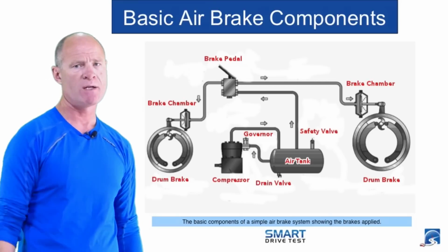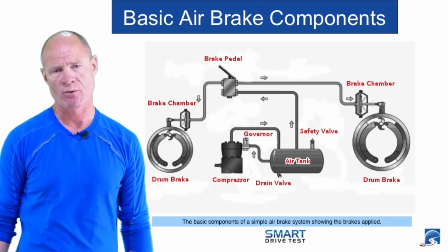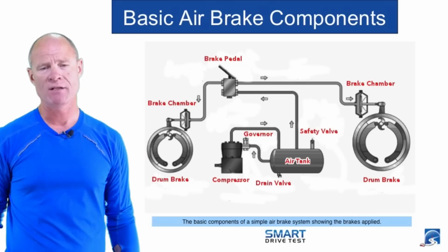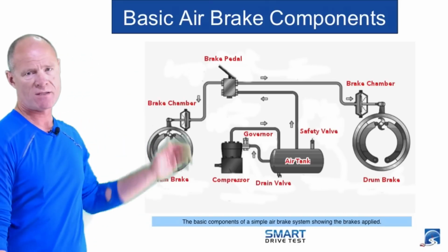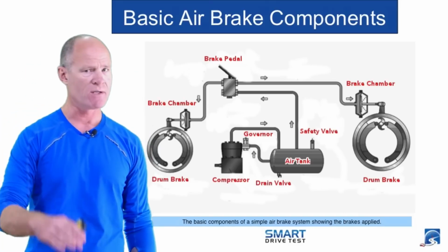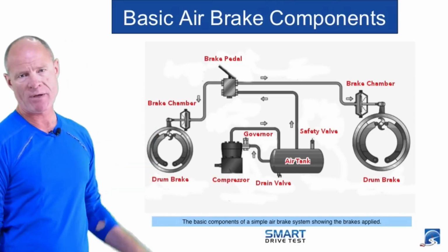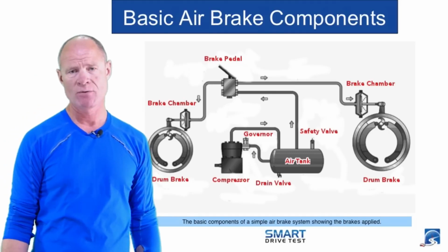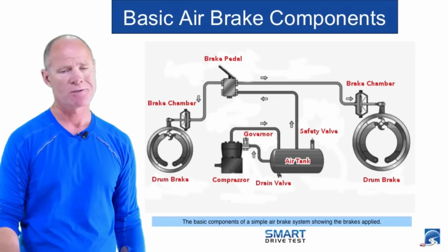That's equipped with air brakes, the service brakes, and the spring brakes. The spring brakes are primarily used for parking and, in the event of an air loss, also for emergency brakes. But for this fundamental system, these are the service brakes, the brakes that you use going up and down the road after you release the parking brakes. The brake pedal can also be called the foot valve or the treadle valve, but for simplicity, we just call it the brake pedal.